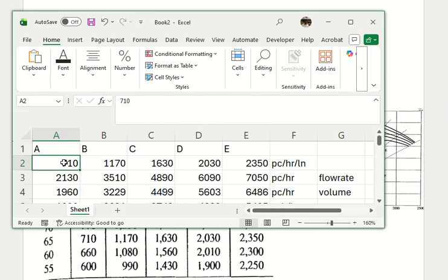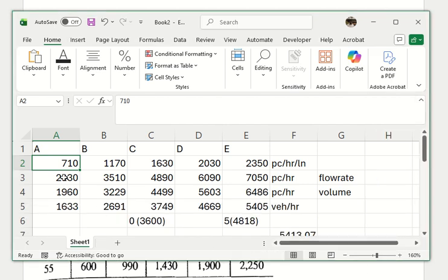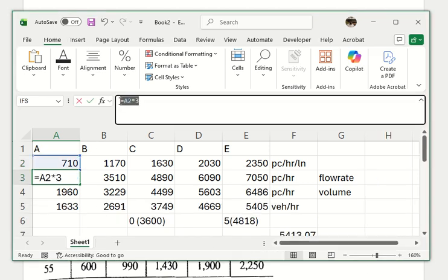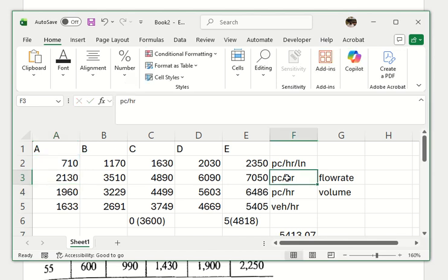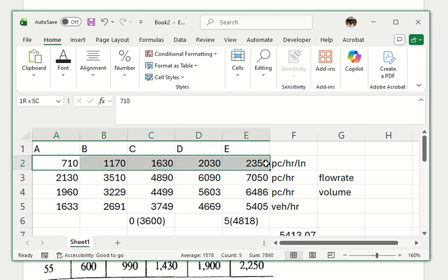So these are the values, as you can see here at 65. I have a 6-lane freeway, so each direction has 3 lanes. First thing I will do is multiply each of them with 3, so the per lane item is gone. They are only passenger cars per hour now. Then I will multiply them with the peak hour factor. Up till here they were flow rates.